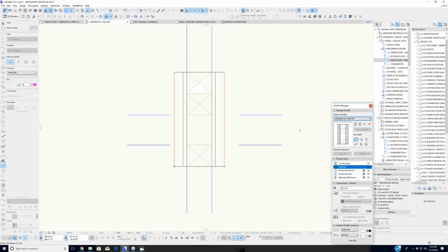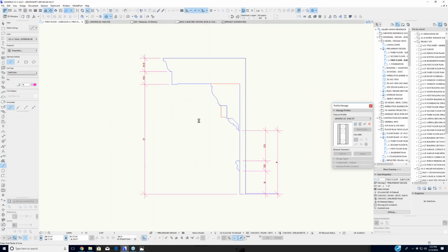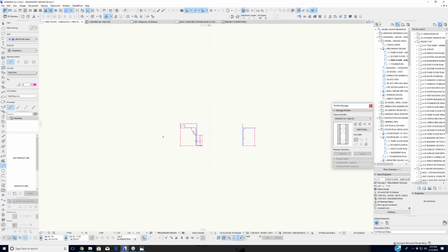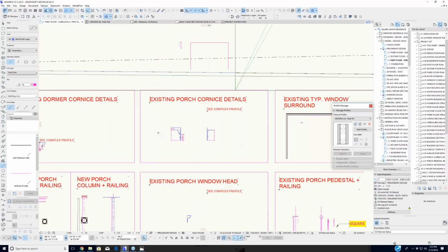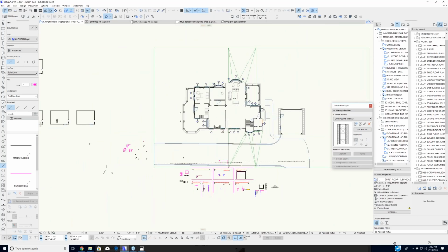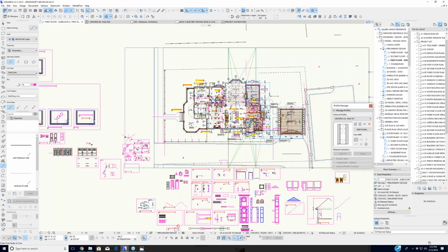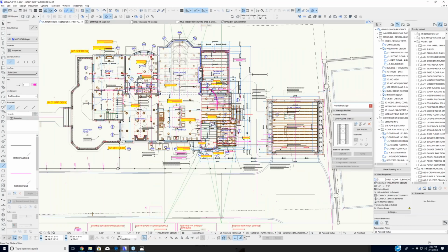So that's where I said it takes a little bit of time to set this up, but the modeling is much faster. Can you cut a section where you have a similar type of wall and show it at the full height? Because I think there are some people who probably don't understand that you've made a short little piece, because you could stretch it from that minimum height to a real 7 or 8 feet or 10 feet height. So if you cut a section, either a real section or a 3D cutaway, then we can look at it.